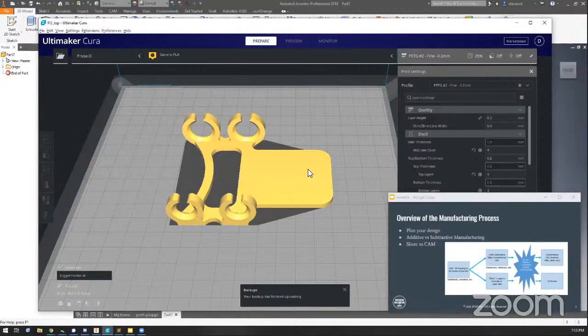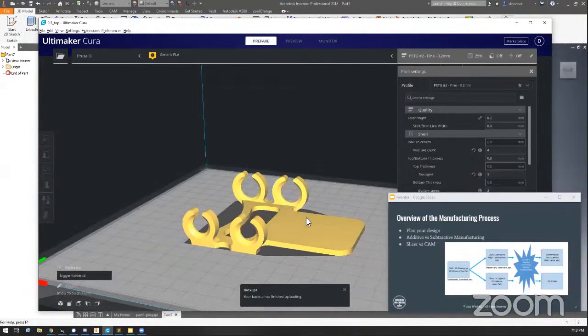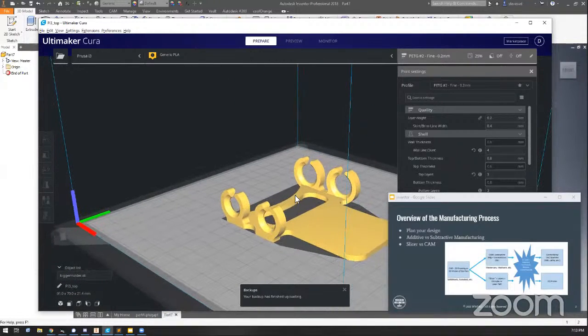You can see here that given how this part is designed, there are pieces that come out from a base piece. Most of the mills that we use for metal fabrication end up only being able to cut in a single direction. For example, at Woodland, where I am a mentor, our mill can only cut mainly profiles.